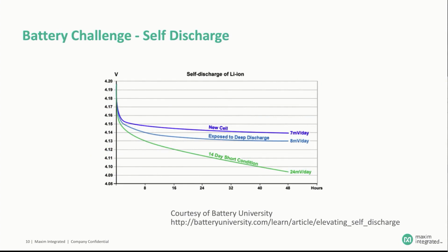One effect that we consider in nanopower applications is battery self-discharge. Self-discharge is a phenomenon in batteries in which internal chemical reactions reduce the stored charge of the battery without any load connected between the electrodes. Self-discharge decreases the shelf life of batteries and causes them to initially have less than a full charge when actually put to use. Other factors affecting self-discharge are how the battery is stored, humidity, and most importantly, temperature.